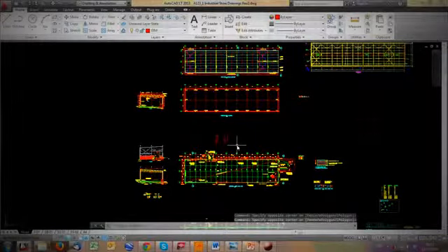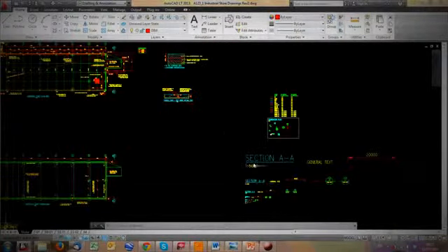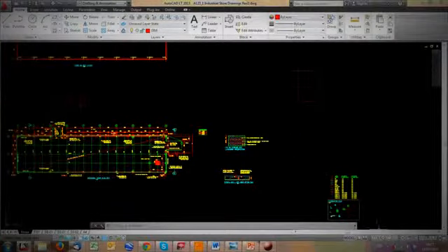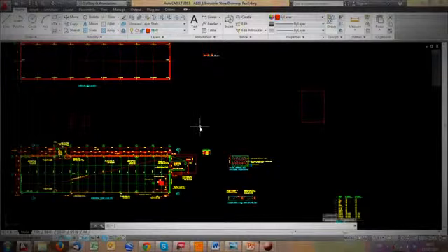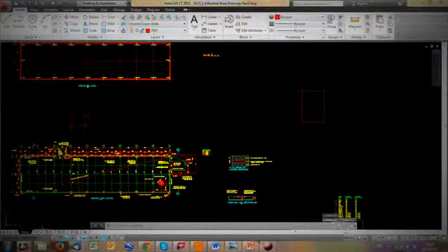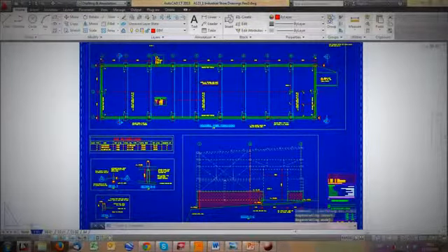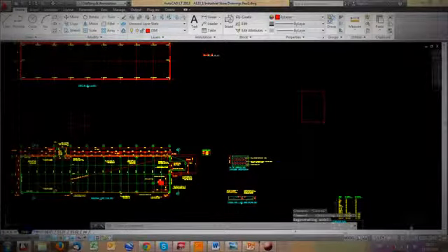I'd encourage you just for now, for simplicity, draw everything at 1 to 1, adjust your dimension tools, and just get along that way. You can, though, in model space, draw things at 1 in 100 next to a 1 in 1 next to a 1 in 50, and they will all come out looking as if you had produced it in Paperspace, but just be very careful of that. And then there are various other tools, annotation styles, etc.